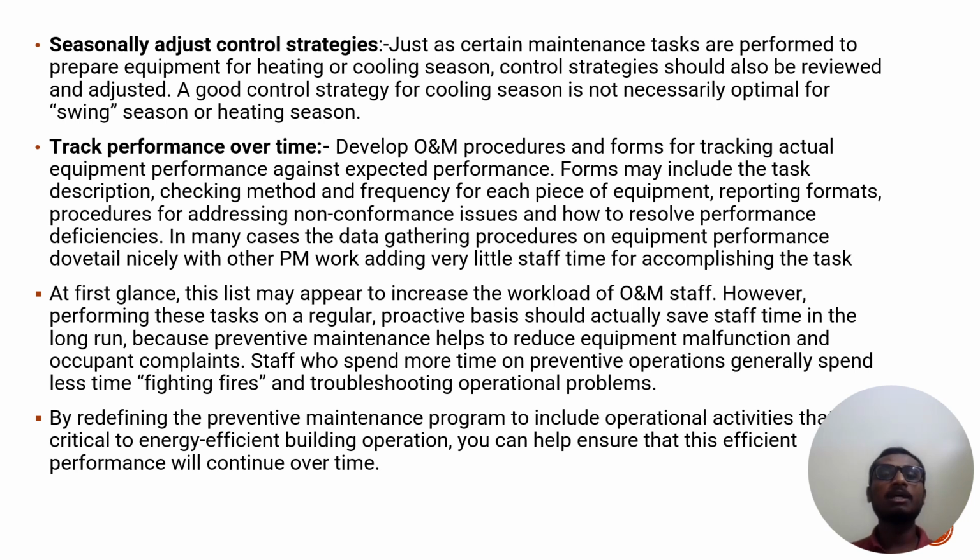At first glance, the task may appear to increase the workload. O&M staff, however, performing these tasks on a regular proactive basis should actually save time in the long run, because preventive maintenance helps reduce equipment malfunctions and occupant complaints. Staff would spend more time on prevention, and generally spend less time fighting fires and troubleshooting operation problems. By defining a preventive maintenance program that includes the operational activities that are critical to energy efficient building operation, you can help ensure the efficient performance will be continued over time.